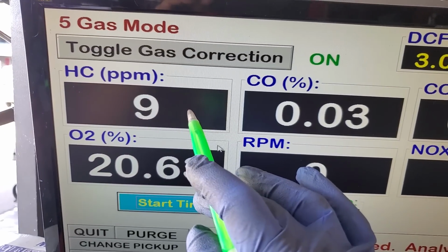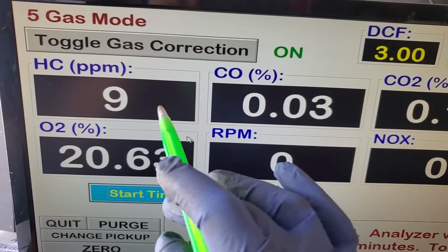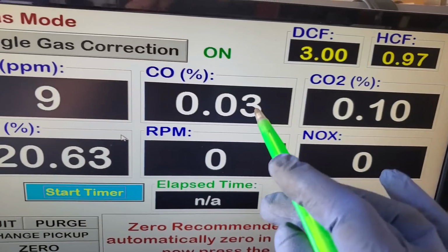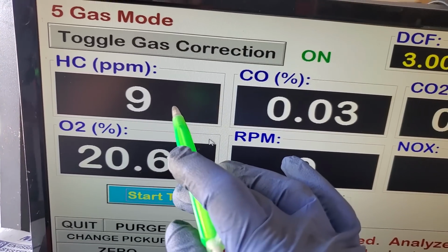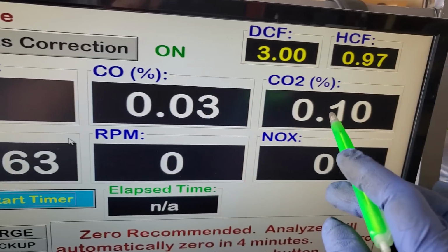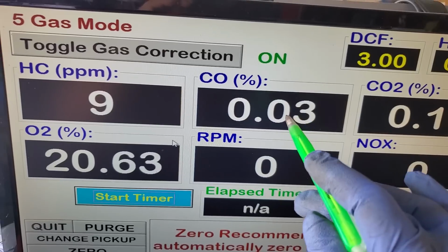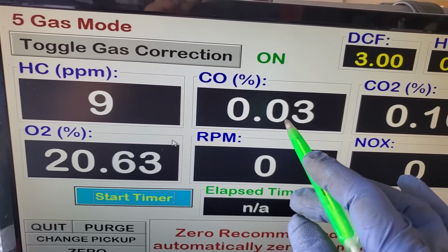More hydrocarbons than there is available oxygen to convert all of the hydrocarbons into carbon dioxide. So you need enough oxygen to burn all the gasoline and have just carbon dioxide left. So in a vehicle, carbon monoxide is usually caused by a rich mixture.